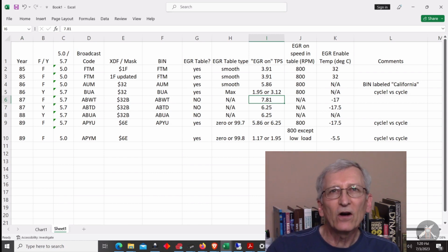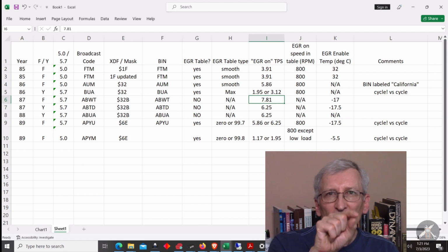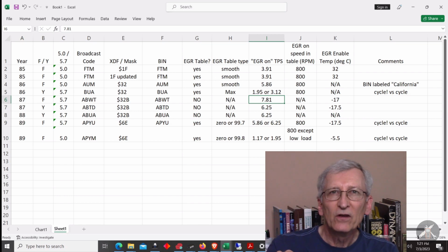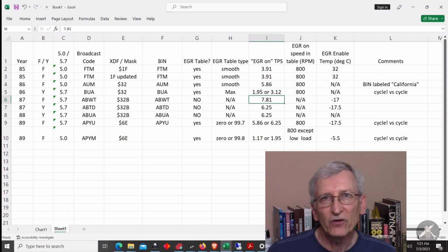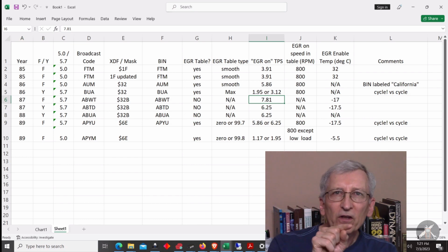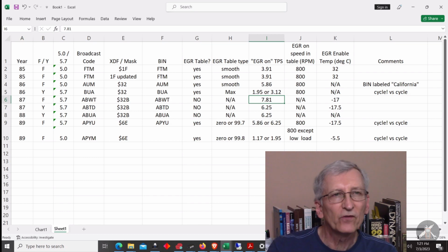And yet the car may pass with flying colors, but in certain little spots, it may exceed what you would expect. So like California, they're doing a dyno test. They're not doing an hour-long profile cycle and adding the whole thing up like we would do in certification. They're hitting 2 or 3 load points and saying, does your car pass at these different load points?